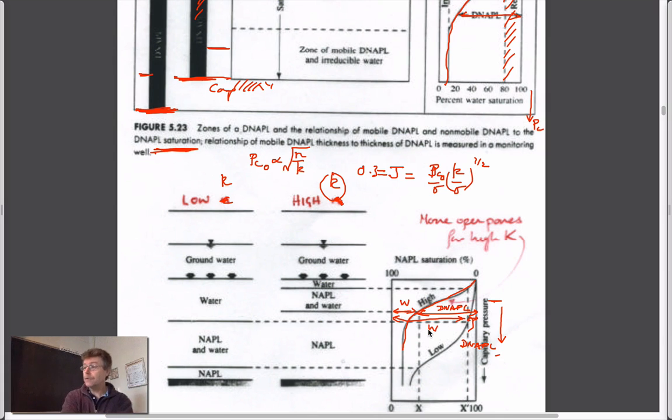I think it's not an easy topic to talk about, but it all logically follows on from these capillary pressure versus saturation curves. And it ultimately allows us to look at these cartoons that we've talked about, that we have a puddle of this sitting here. If you have other capillary barriers that exist here, you have these little puddles that sit on top of these capillary barriers, and above these capillary barriers you have these chimneys. It fills this up, it cascades off the side, gets captured, cascades off this side, gets captured. Doesn't necessarily have from side to side.